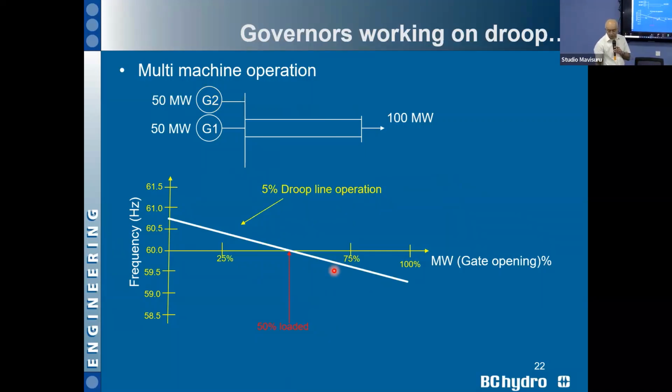Assuming that when the grid is bigger, you don't have to put another unit into the isochronous mode. So this is kind of like I try to mimic the bigger system. Previously, I tried to mimic the smaller system, which is working all right with one unit in isochronous and the other units on droop. But when the system becomes bigger, one unit cannot fulfill the load variation, because assuming 2000 megawatt, 10% of 2000 is like 200 megawatt. You need to have about 500 machine to have that 200 load.